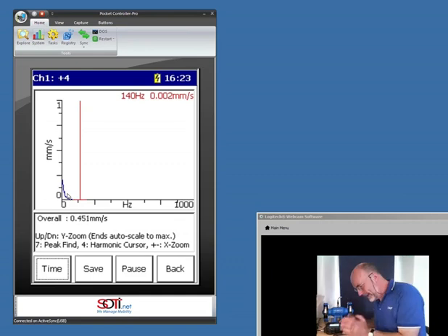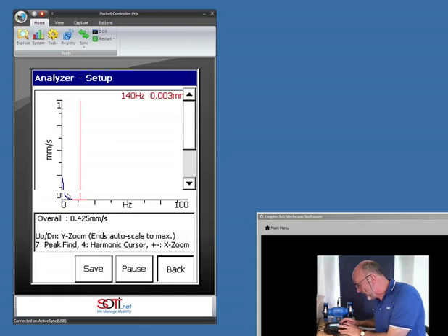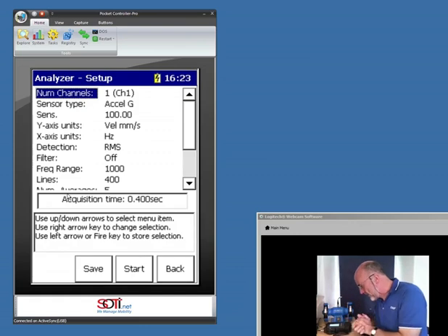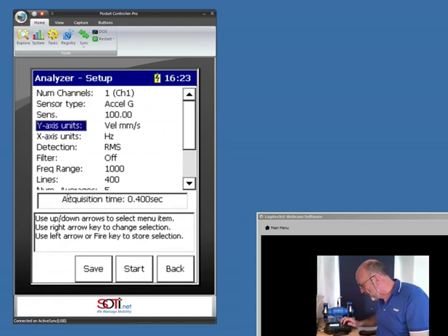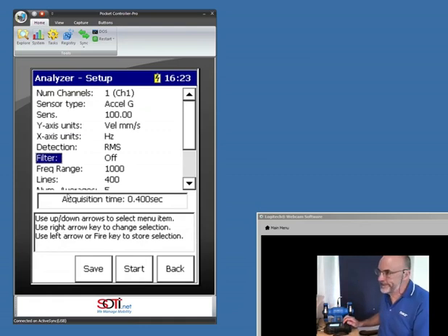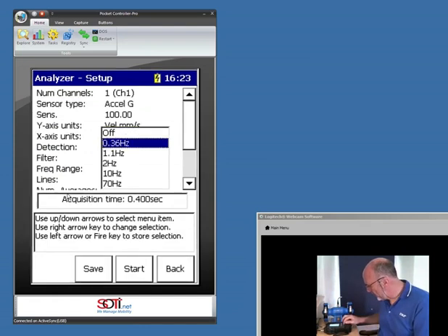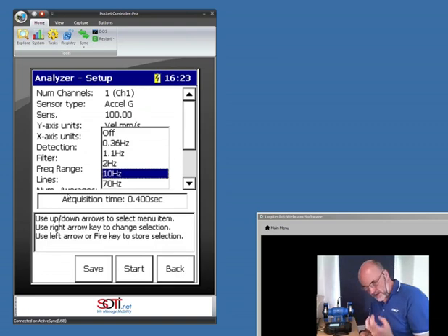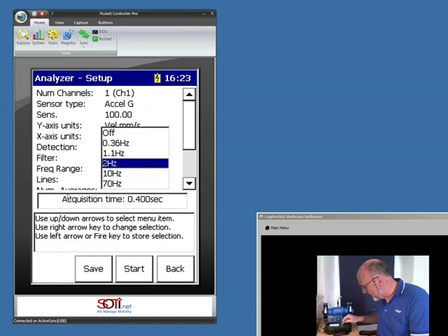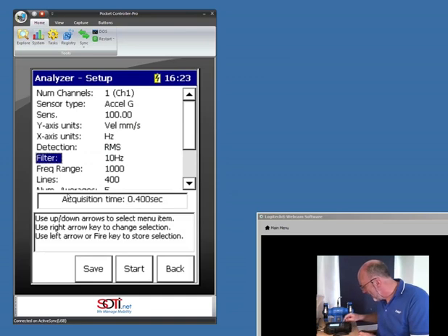So one of the basic things that you're going to be doing when you go out there with your hard hat on, your ear defenders on, and you want to get rid of seismic vibration, we have this thing called a filter. And it's prudent when you're doing machinery-type vibrations that you use a filter. Most ISO standards will tell you to get rid of anything below 10 Hertz, which is 600 revolutions per minute. Beware that some standards say 2 Hertz.